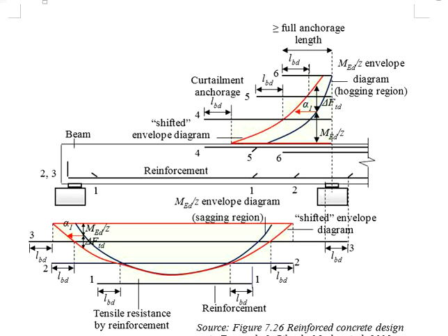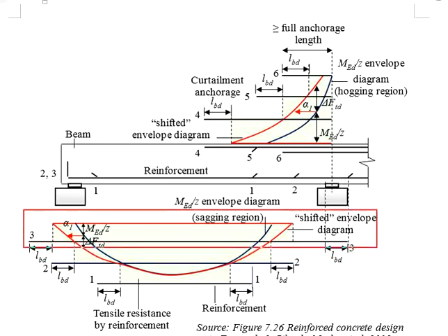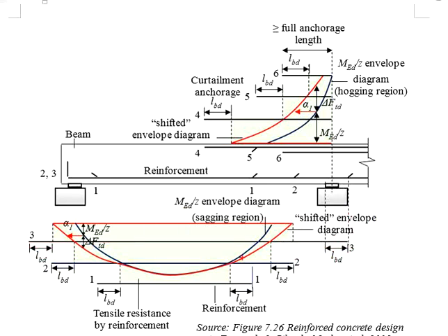This model here disregards the contributions in terms of the development of tensile stress along the anchorage length. And then, where do we need to stop the reinforcement? It will be at the end of the anchorage length. The one that we discussed previously subdivides the amount of reinforcement bar into 3 different groups. You deal with the first group first. Find the intersection. Add up the second group of the reinforcement plus the anchorage length. Determine where the reinforcement is to be stopped.